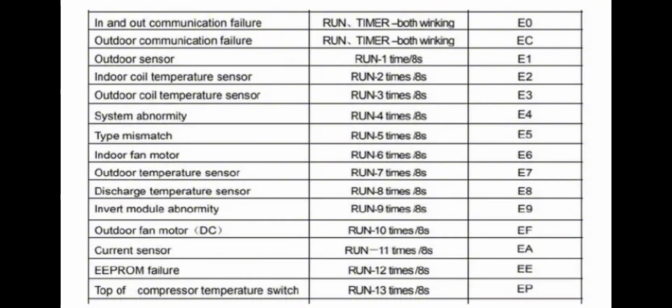We have EU fault, which is voltage sensor fault, and EH fault, which is outdoor intake temperature sensor. Both you can check the wires, replace the sensor, or replace the power source board.